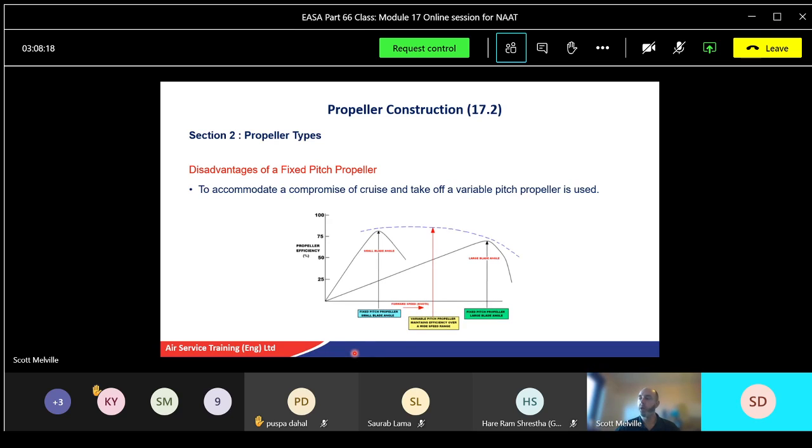Okay. So there's a little diagram here for the fixed pitch. We've got propeller efficiency. Remember, it gets about 80–85% maximum. So a fixed pitch propeller, with relative forward speed. So not very fast there, but at that forward speed it's about 80% efficient. And any faster than that with a fixed pitch, the efficiency drops off. A variable pitch one is almost like a gas turbine engine, very, very linear, up till a certain aircraft speed where it can't go any faster, and then efficiency will drop off rather rapidly.